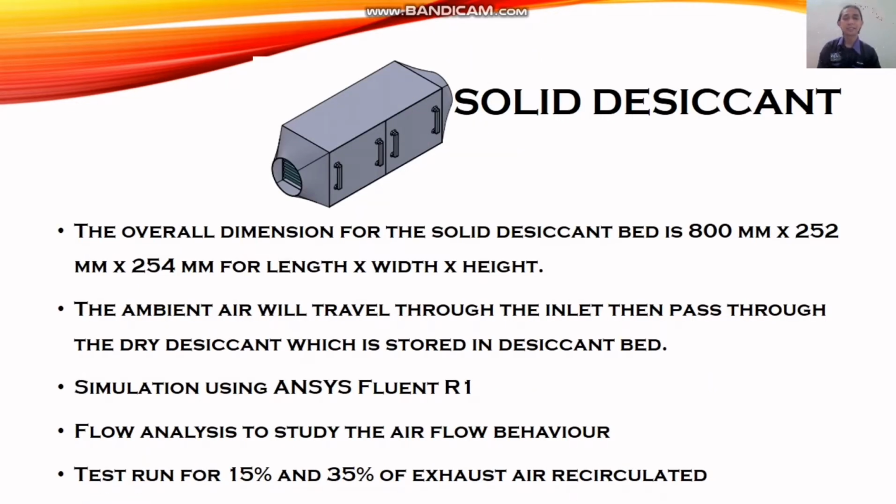This is the solid desiccant. The overall dimension for the desiccant bed is as above, and the ambient air will travel through the inlet here, then pass through the dry desiccant, which is stored inside the desiccant bed, which are the silica plates. The simulation will be run using ANSYS Fluent R1, the flow analysis to study the airflow behavior inside the solid desiccant, and there will be two test runs, one for 15% and another one for 35%.